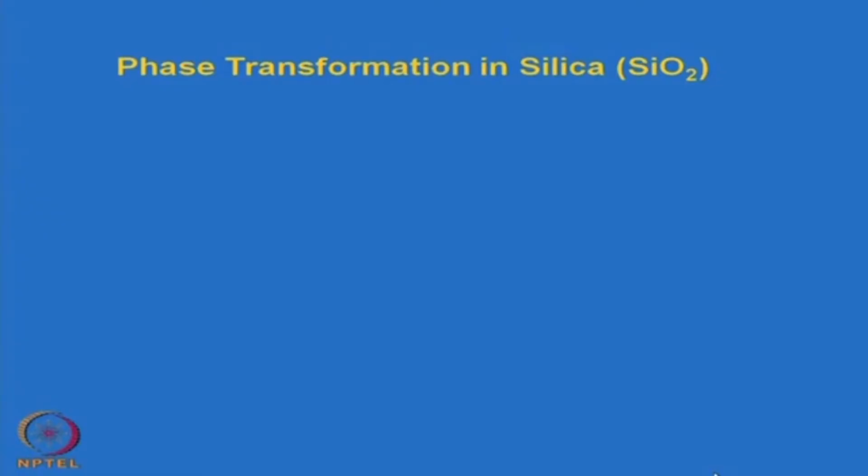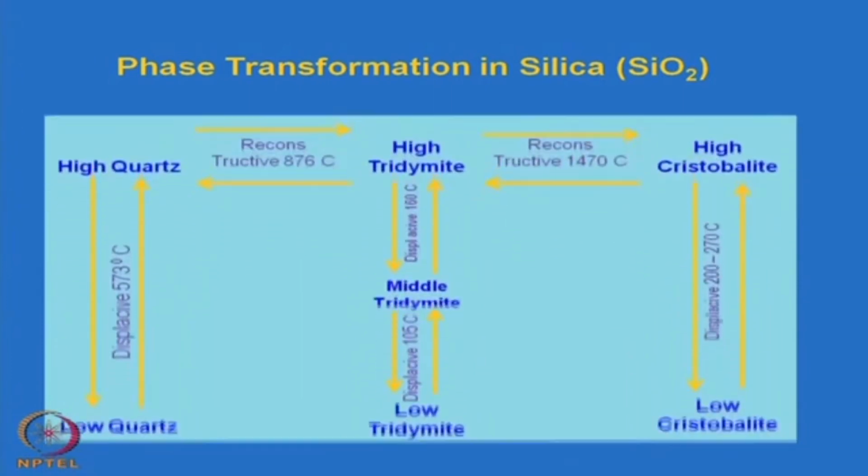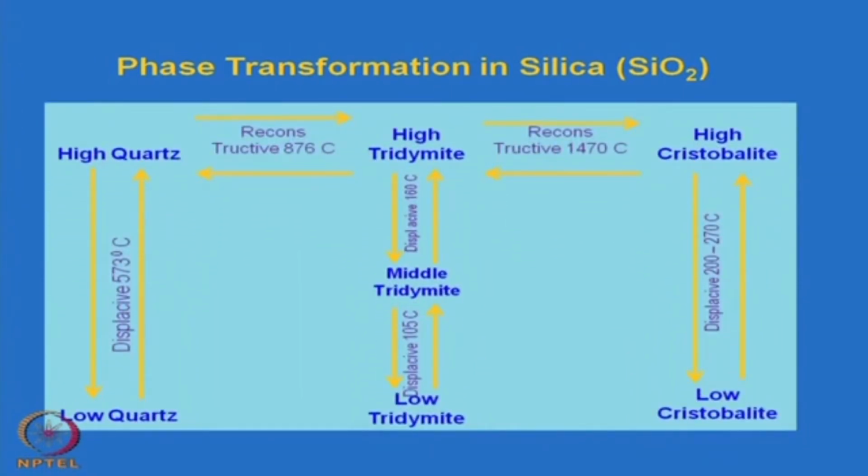Silica, SiO2, is basically composed of silicon oxygen tetrahedra, and we have seen how this silicon oxygen tetrahedron can be combined with other cations and form a series of different silicates. But pure silica is also a very important raw material for ceramics, not only for the traditional ceramic group, but sometimes also for advanced ceramic products in combination with other oxides.